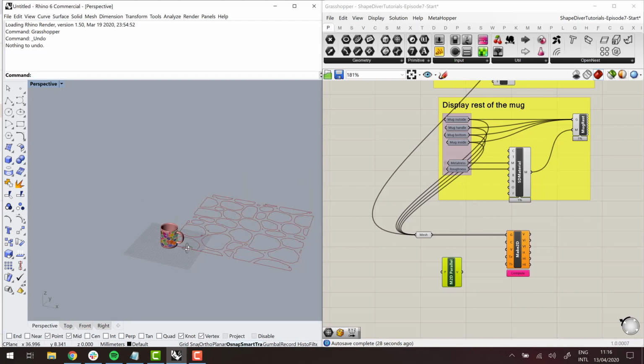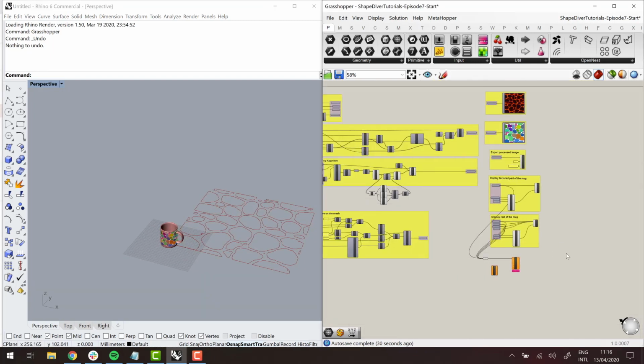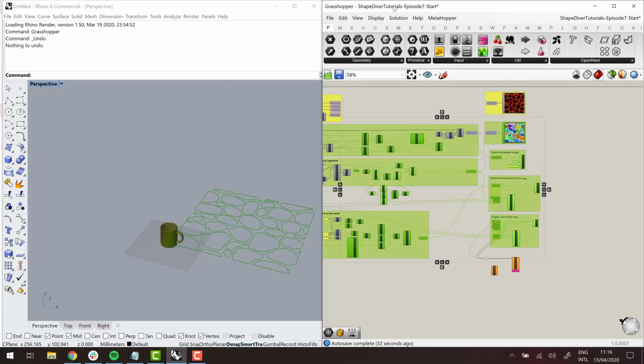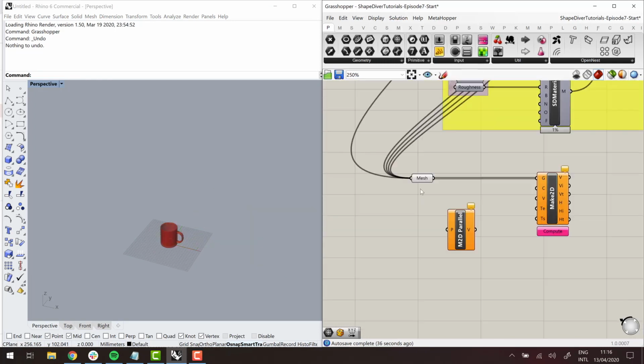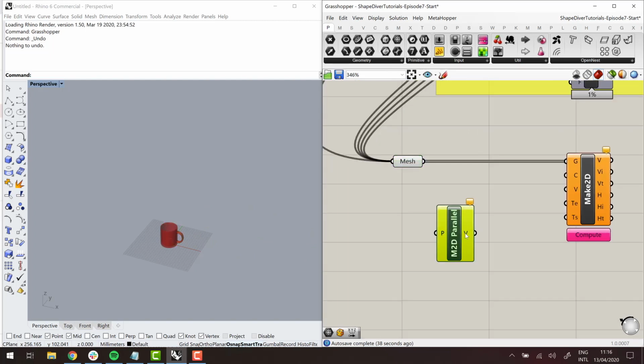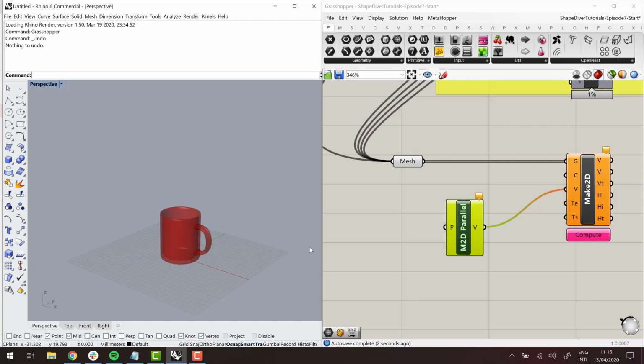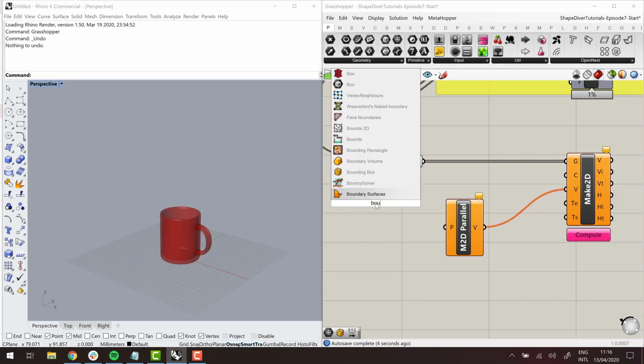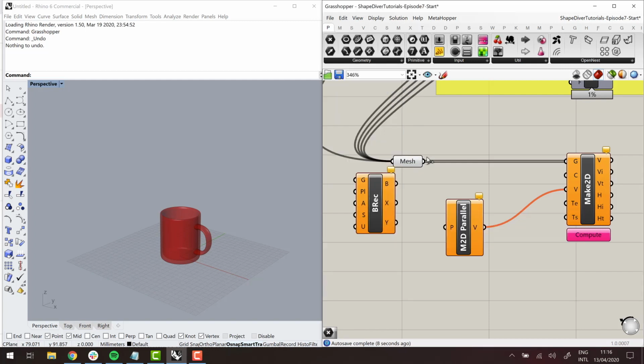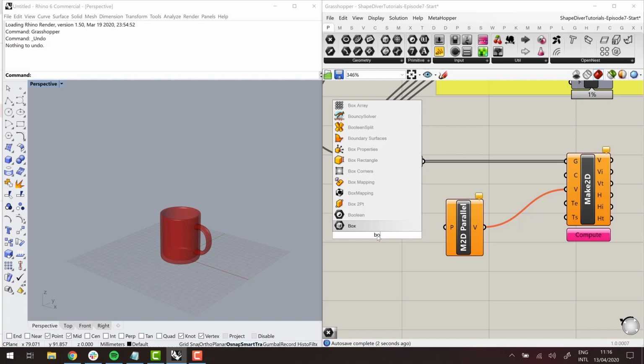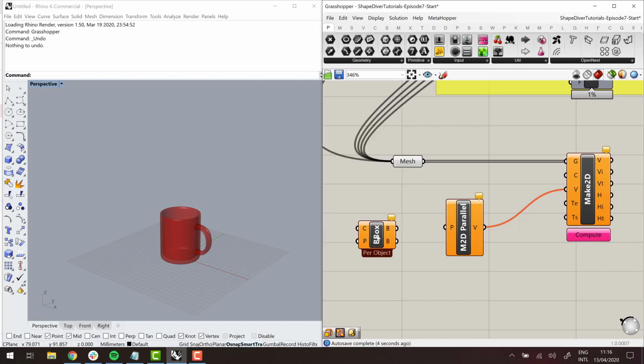In this case, we'll use a parallel view to draw in the XZ plane the projection of the geometry. So first, to make it a bit less messy, we're gonna hide everything else, just show what interests us. Here a parallel view, and what I want is basically to draw in the XZ plane along the bounding box.